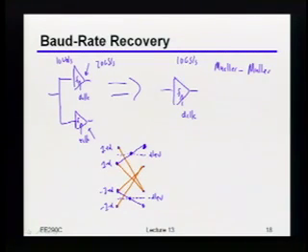Slope's kind of small. Yeah, the slope of the red ones is larger, right, than the blue ones. Why is that important? With the same voltage noise, it could throw your phase off more. Yeah, exactly. Remember, anytime you have something that has a slower edge rate, for the same voltage error, it's going to translate to a larger error in time, right? So that's actually exactly why with these kinds of systems, you often will have worse performance by doing something like this loop unrolled type of system than you would by having the 2x oversampling.